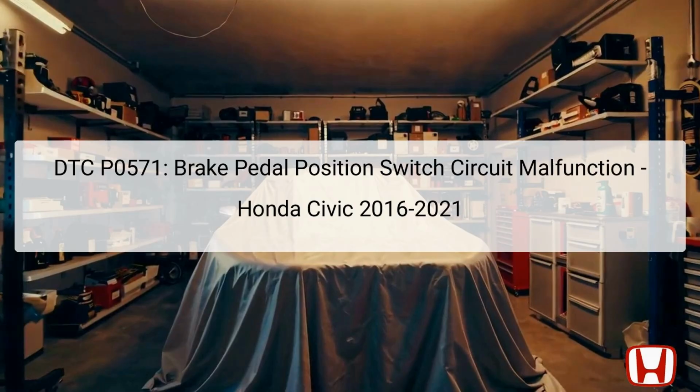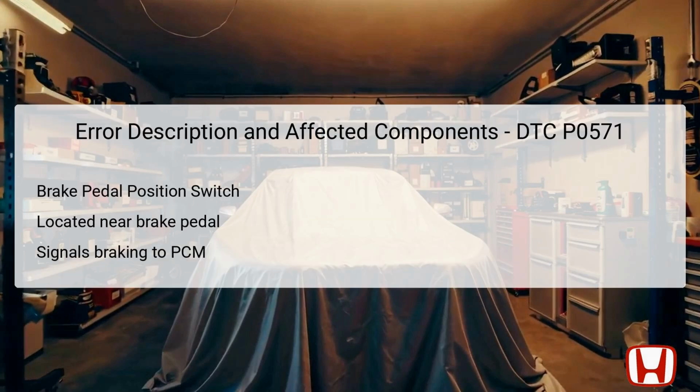If this switch fails or has a poor connection, it can trigger the P0571 code and create issues in vehicle operation. Diagnosing such a code involves understanding both the electronic and physical aspects of the brake system. The error P0571 points specifically to the brake pedal position switch malfunctioning, which is vital for ensuring the operation of the brake lights and the overall functioning of the vehicle.